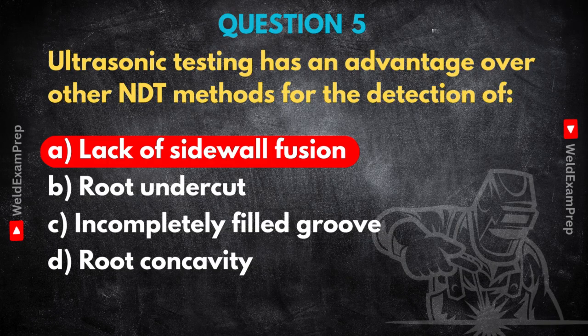And it's typically a planar defect, meaning it's relatively flat, like a crack. These flat internal surfaces are excellent reflectors for ultrasonic waves, especially when the sound beam hits them somewhat perpendicularly. UT is really sensitive to these kinds of flaws, even deep inside the material. So it's good at finding those flat internal gaps. Precisely.